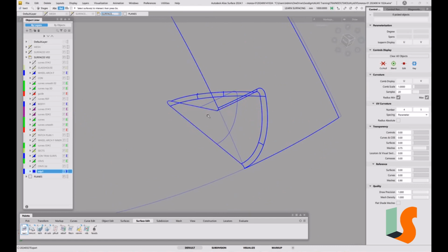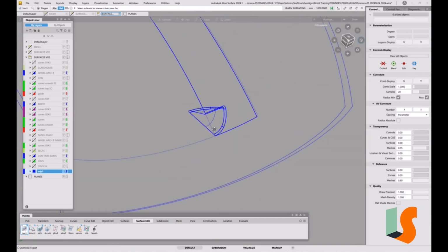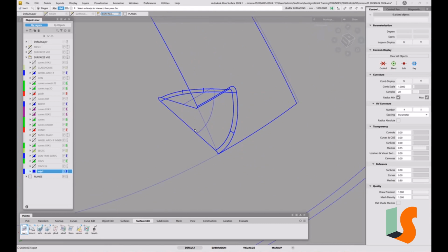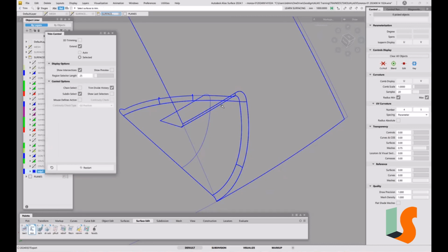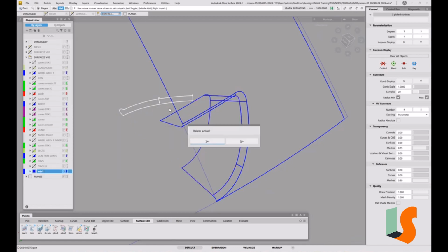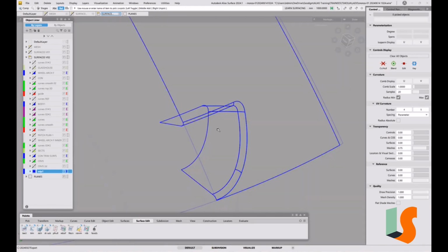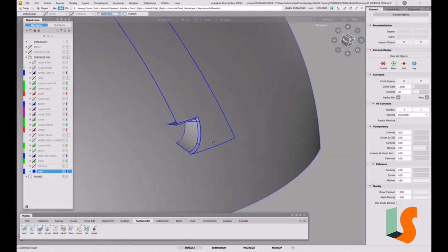And then we want to, yeah, actually we haven't got the bit down the center. We can trim all of these out. So I'm just doing a trim on those. Let me go into the trim function, because maybe I've got this set up with that. If you take that off, then it becomes easier, because then it's not going to get confused. These surfaces we can chuck in the bin, or you could put them into another layer if you wanted to. Now I've got a duplicate on there, so I don't need that one. That's just a duplicate, just making sure.